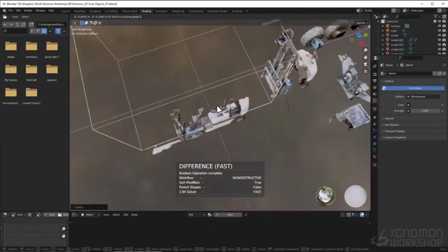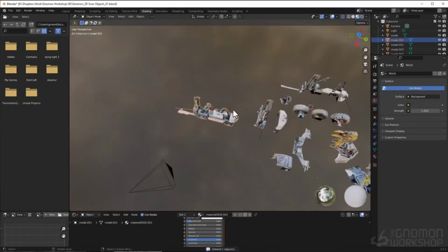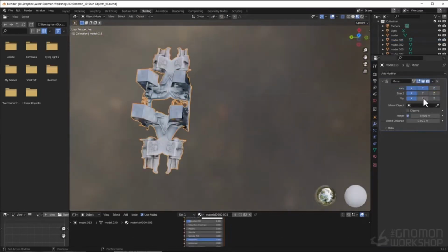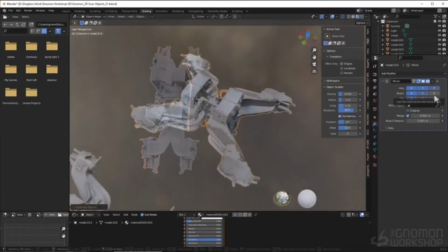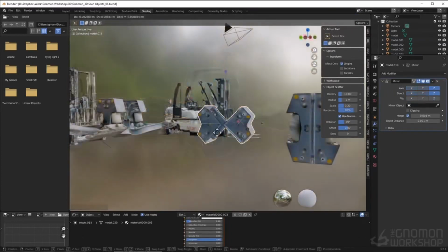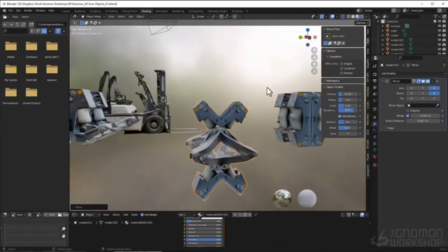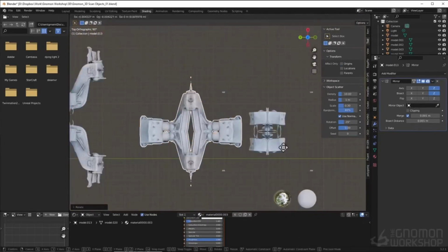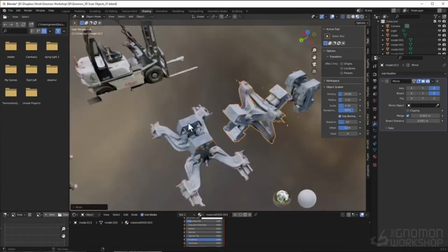And the sides have some cool shapes, so I'm going to extract those and see if there's something I can make from them later. The front claw thing from that digger has some really nice shapes. I'm applying the mirror modifier and playing around with the settings to see if there's any new shapes I can make. I'm also moving the origin around to change where the mirroring occurs, which makes some happy accidents. When I find something cool, I copy the object across to save it and then experiment some more.